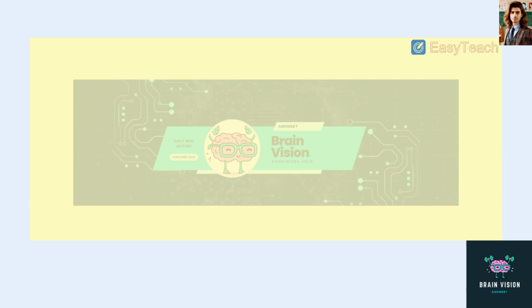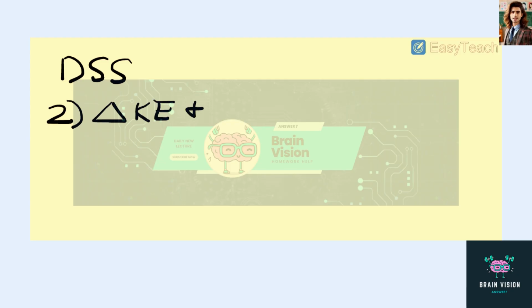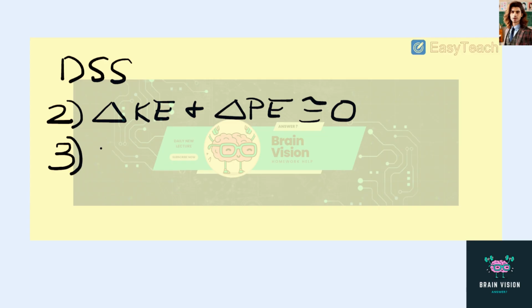So first thing we're going to do is write down our assumptions. First we're going to assume that this is a steady state process and there's no changing with time. Next we're going to assume that changes in kinetic energy and changes in potential energy are negligible. And we're also going to assume that work and heat interactions are also negligible.